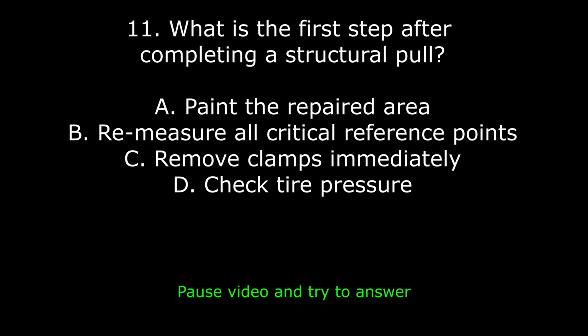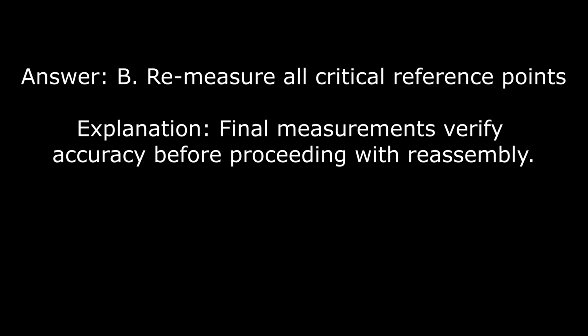11. What is the first step after completing a structural pull? A. Paint the repaired area. B. Remeasure all critical reference points. C. Remove clamps immediately. D. Check tire pressure. Answer: B. Remeasure all critical reference points. Explanation: final measurements verify accuracy before proceeding with reassembly.